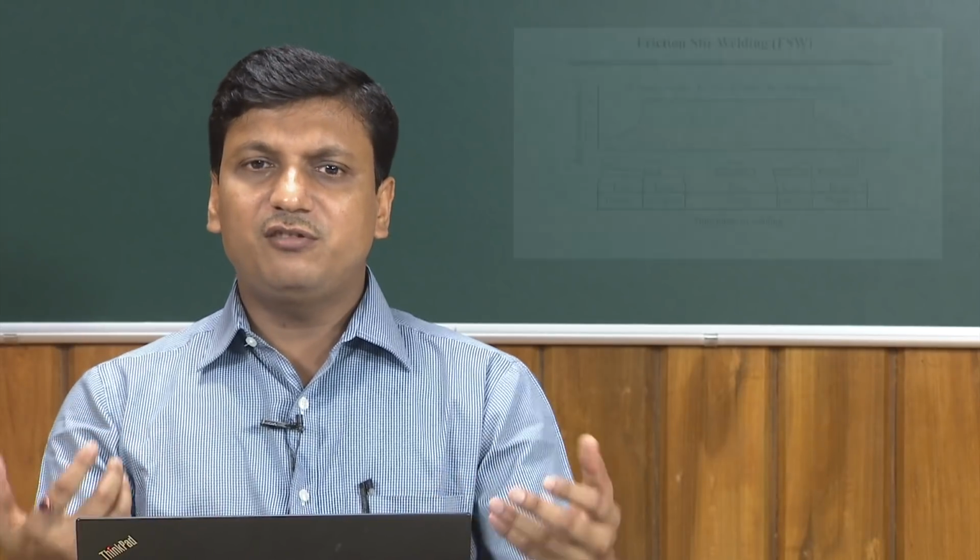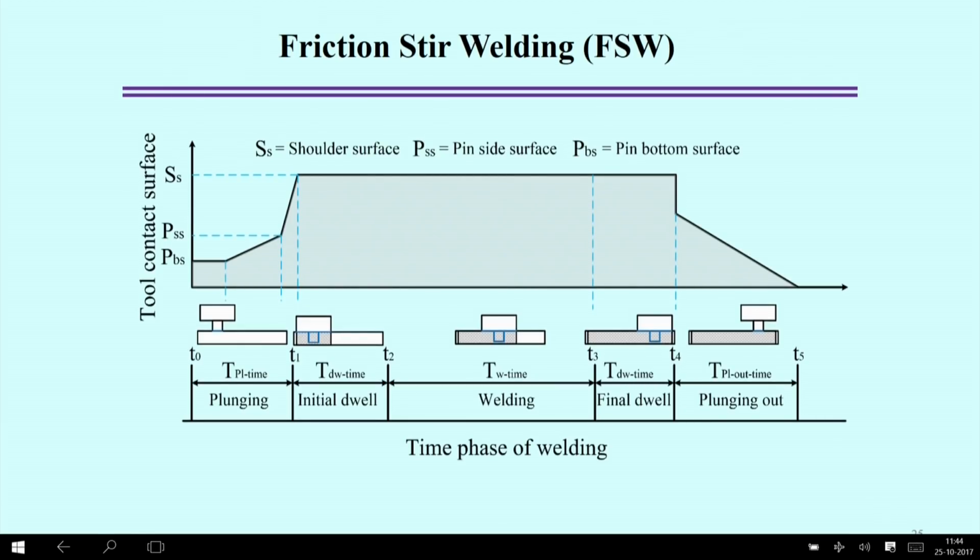Now, in the friction stir welding process there are different stages. If you look at the complete process, first, after fixing the workpiece or substrate material, it is necessary to bring the tool into contact with the workpiece. So, in that initial period, at a fixed position or fixed axis, the tool is given a vertical motion towards the workpiece surface; that is called the plunging period.